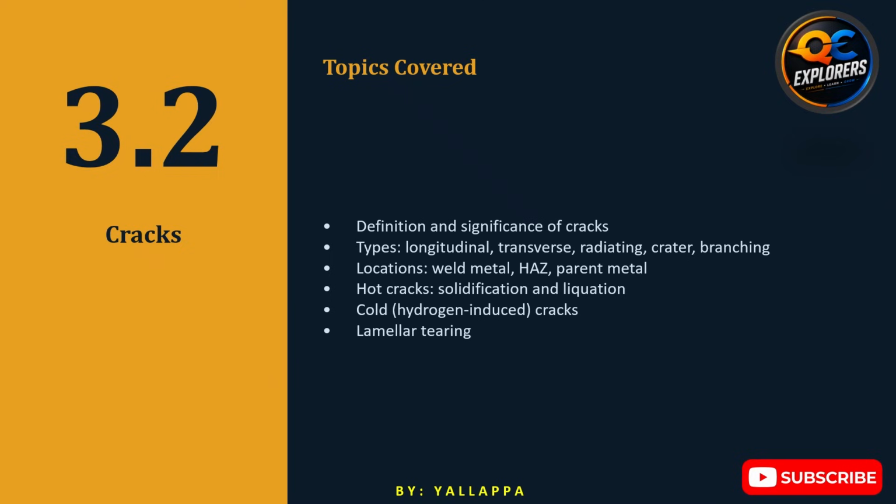Similarly, a stepped crack in rolled plate may point toward lamellar tearing. So don't approach crack identification by memorizing isolated photographs. Instead, ask: where is the crack? What direction is it running? When did it form? And what material or welding condition could have produced it?